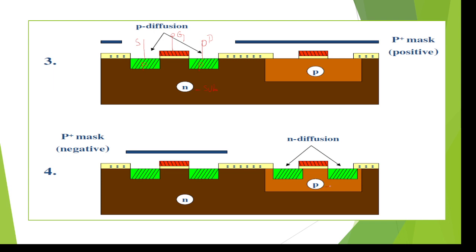It is a P substrate, meaning it has holes, so there is one chance to design an NPN transistor. We diffuse by heating this material, diffusing electrons into the P substrate using a mask, because the mask keeps the remaining area unaffected. That's the reason they use a mask here. So the right side transistor is also designed.